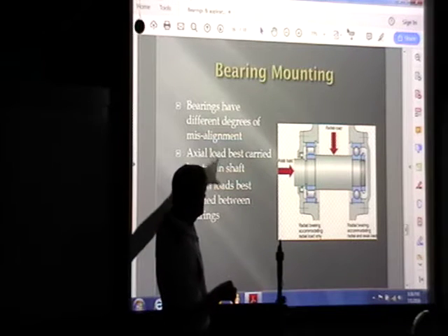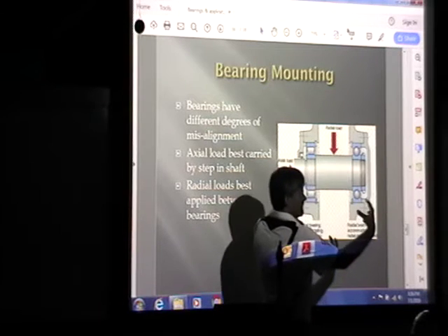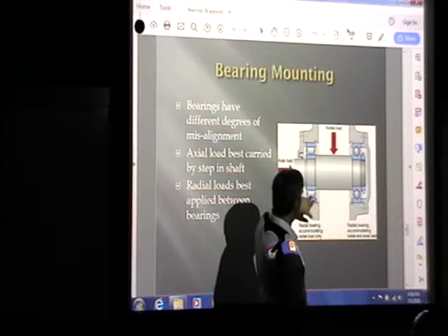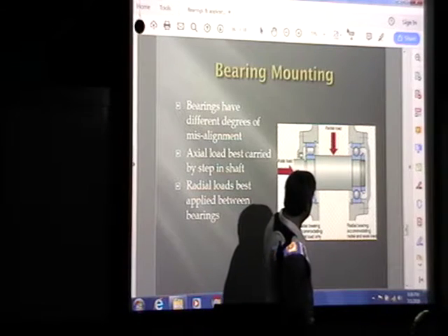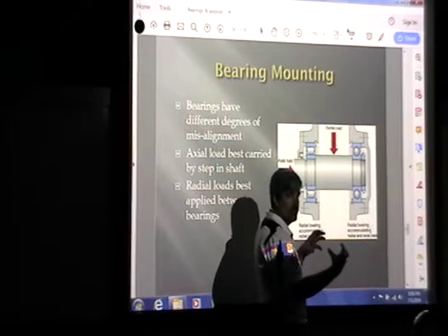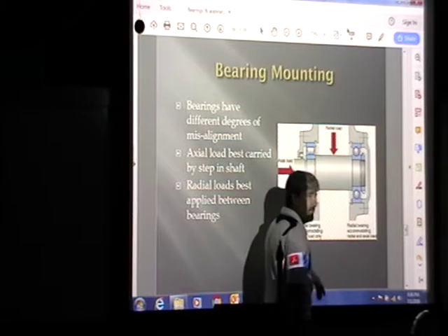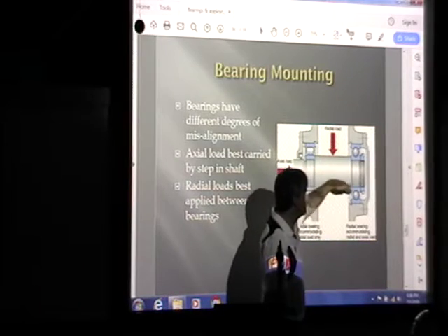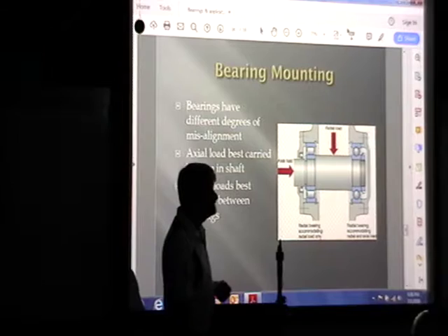So this is kind of re-emphasizing what I just talked about. In each of these bearing sets here and here, there's a certain amount of axial play where they can align to each other. But depending on the design of the bearing, if there's no axial play, then you've got to machine this hole and this hole directly in alignment. Or you've got to have a way to align those at assembly such that they're in line. Otherwise, if you get those off center from one another, the shaft will end up being like this, and you're going to eat up all your power trying to get those bearings to turn.